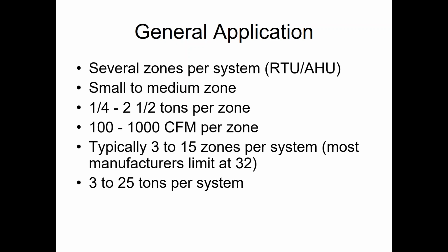You shouldn't make the assumption that VVT is going to be less expensive than VAV. From a zoning standpoint, it's pretty much the same cost. You're buying dampers, you're buying controllers, you're buying sensors. Yeah, the VAV has the CFM static pressure inlet sensor as well. But other than that one widget, the controls is pretty much the same cost. The air handlers, if you do it right, you're going to have 4 or 5 rooftops on a building versus one big VAV air handler on a building. And it's probably going to be a wash there for cost. If you do it wrong, one really big constant volume rooftop, yeah, your equipment will cost less, but you're going to eat it later in terms of callbacks.